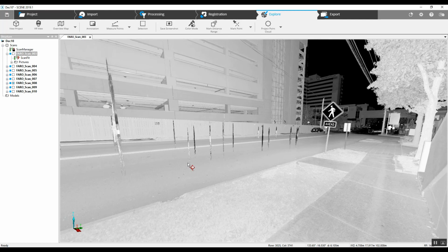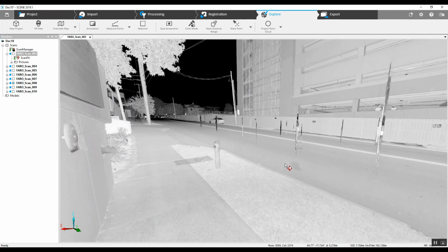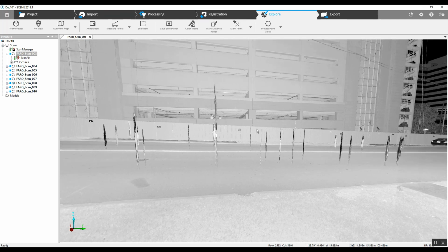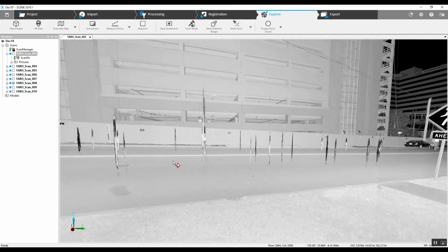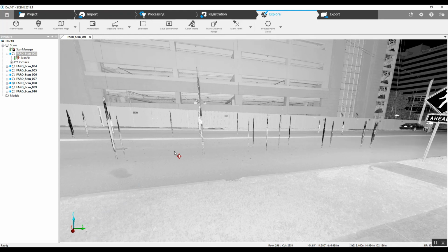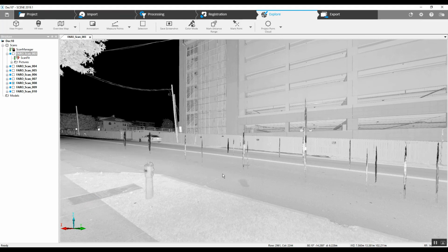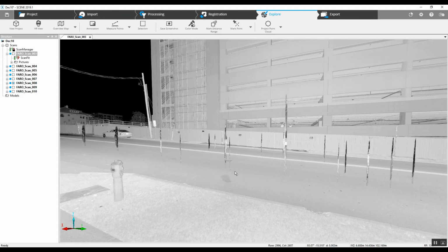This is easiest to do before color is added because you can actually see where the vehicles are. Once you add the photographs, if you've ever done much scanning with vehicles, you'll know that the camera coming by minutes after the 3D laser images were captured will be in the exact wrong spots. So the indicators of color and where the vehicles look like they are with the photographs is absolutely not an indicator of where the actual 3D data is that needs to be erased.